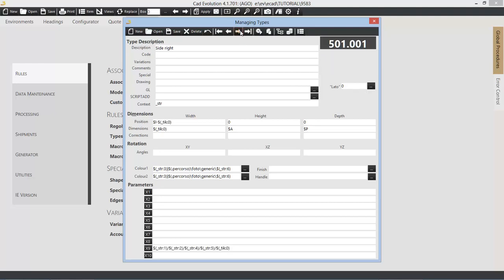In addition, we have built a subtypology for the right side, where the only difference from the left side is the position of this right side. Said this, let's move on going quickly through the different typologies. Let's observe the position and the dimension of the shelf. Obviously, we try to use as many formulas as possible. To insert a specific position is of no use. To insert a generic dimension linked to the formulas makes the object very parametric and more adaptable to the context.